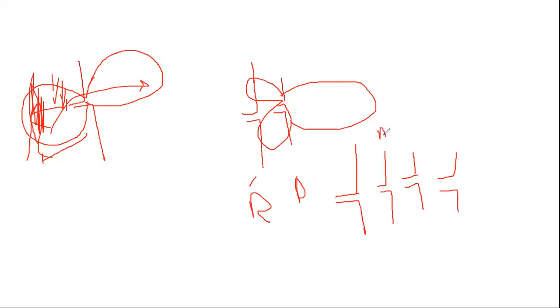This is the driven, this is the director, this is the reflector. Then there will be some minor loops, and this director will also convert this beam into a narrow beam, and that is why the directivity will be large.